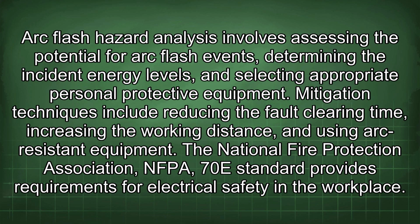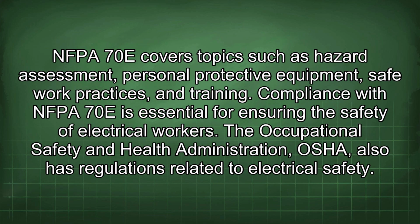Arc flash hazard analysis involves assessing the potential for arc flash events, determining the incident energy levels, and selecting appropriate personal protective equipment. Mitigation techniques include reducing the fault clearing time, increasing the working distance, and using arc-resistant equipment. The National Fire Protection Association (NFPA) 70E standard provides requirements for electrical safety in the workplace. NFPA 70E covers topics such as hazard assessment, personal protective equipment, safe work practices, and training.